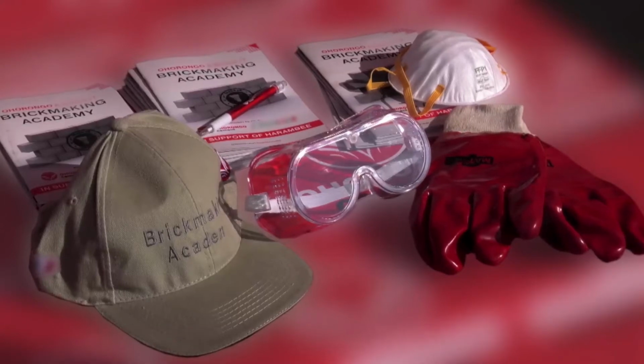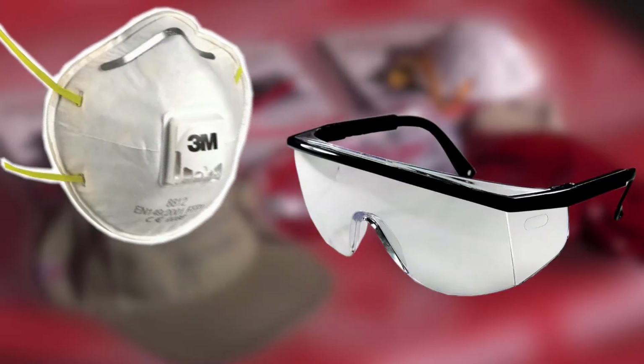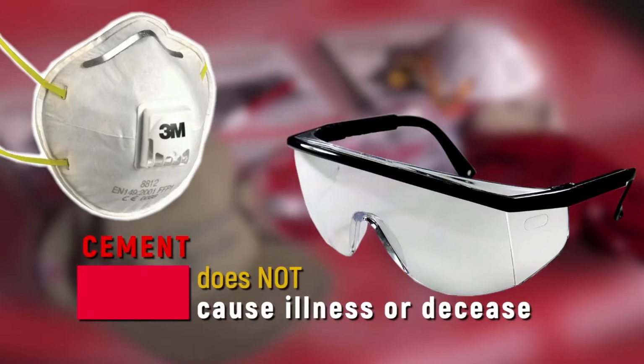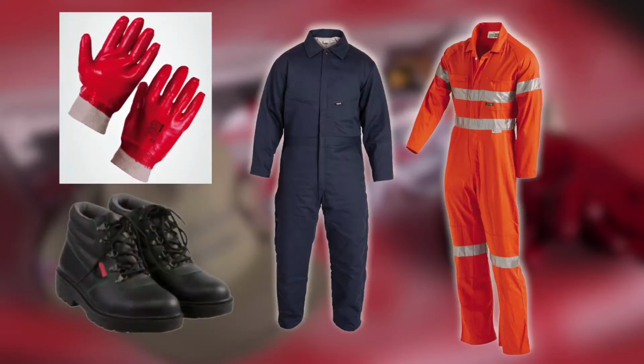In order to protect yourself, you would require the following safety gear. Safety glasses to prevent dust and small objects from harming your eyes. Dust masks to prevent dust from entering your lungs. Take note, cement does not cause illness or disease. However, it will cause throat irritation and dryness. Protective clothing and gloves to prevent skin irritations, as the high amounts of lime can dry out your skin. Safety shoes to protect your feet at all times.